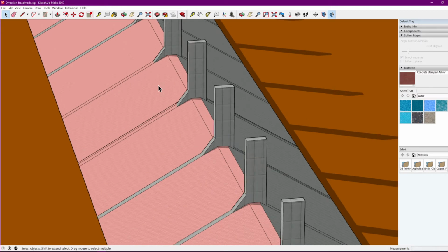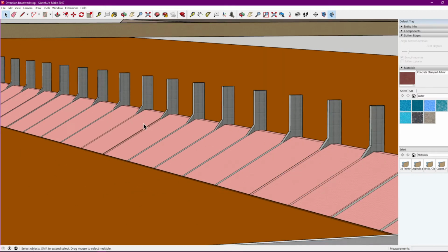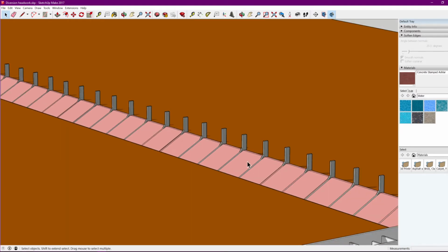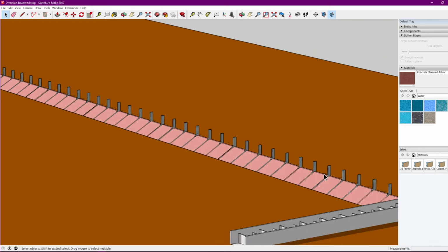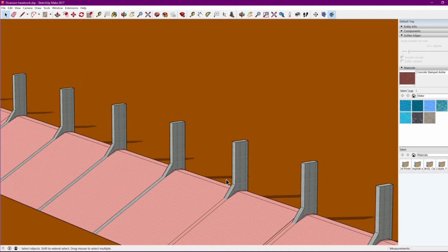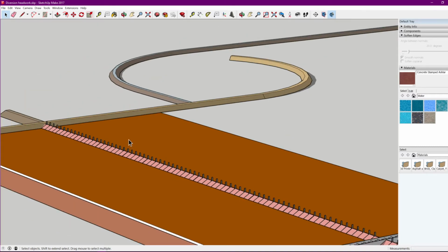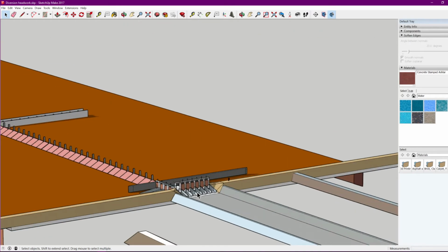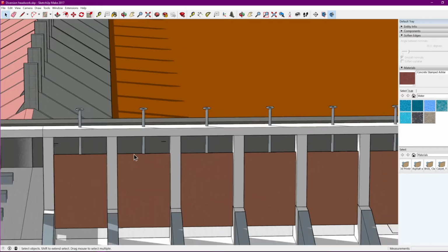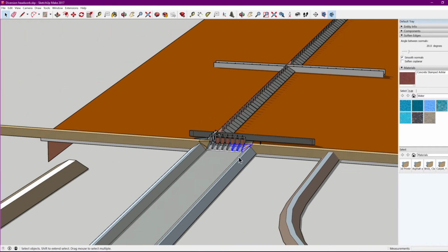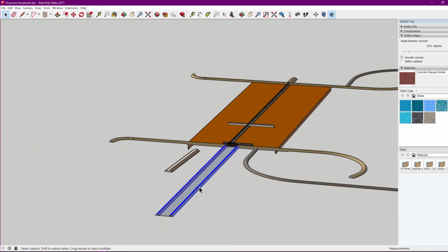So weir is basically like a small dam, but one difference is that we also allow water to flow over the weir, unlike a dam. Generally, we construct a spillway near the dam so that the excess water can be released, but weir is designed to carry water above it, to allow water to flow over it. So this weir will raise the water level in its upstream, and then we can divert that water through these gates, either by opening or closing these gates, and then this canal can carry that water to agricultural fields.